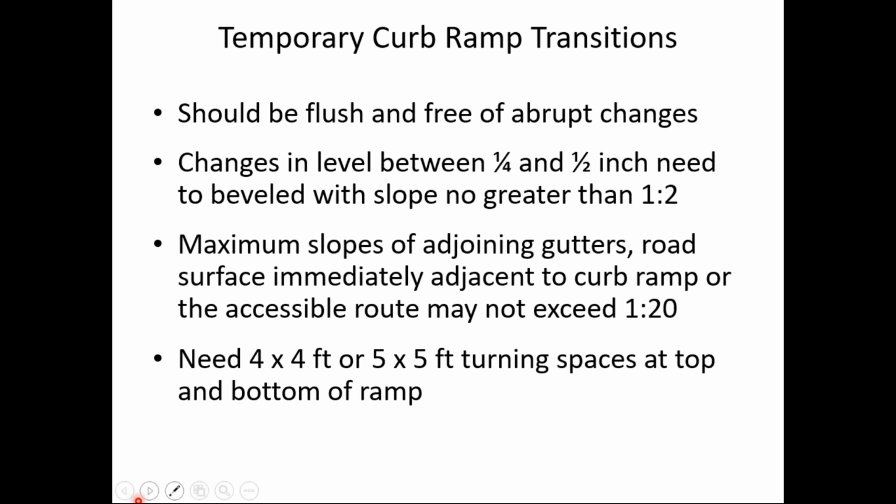The entry onto the ramp in both directions should be flush and free of abrupt changes. Remember, we talked Tuesday about how changes in level between 1/4 and 1/2 inch need to be beveled with a slope not greater than 1 to 2, or 50%. And of course, we need a 4 foot by 4 foot or 5 foot by 5 foot turning space at the top and bottom of the ramp.